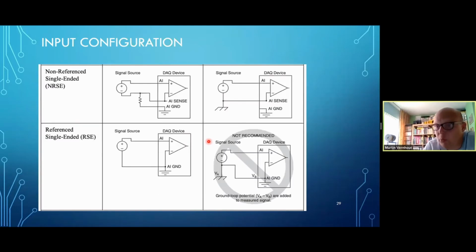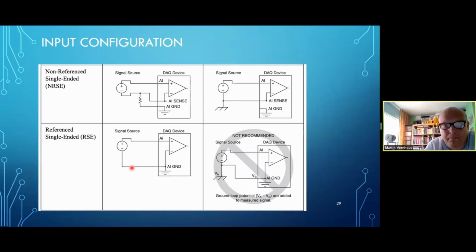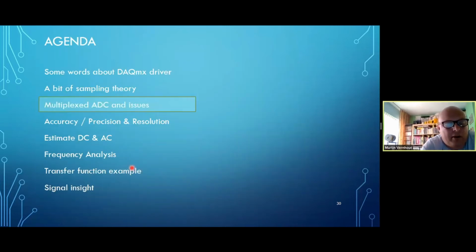And if you mess up, if you do not use the right one, you will get a not optimal result. Sometimes you sacrifice a little bit of that because it's just easier to connect a reference single-ended signal and then have many of them. Sometimes you want best, and then you might go for differential signaling. All right. So there are a lot of things which actually can go wrong, and you need to care about if you want to take your first measurement.